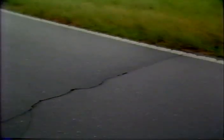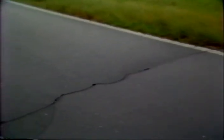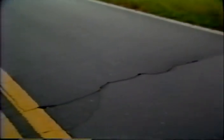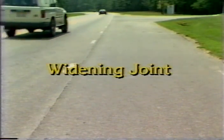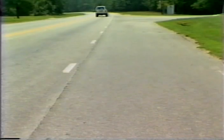Block cracks are not a load-associated pavement distress and do not represent a structural failure of the pavement. However, if these cracks are not sealed, water can freely enter the base and subgrade. This will weaken the pavement and lead to structural problems. A widening joint also needs to be sealed when open. Usually, a crack will form along the joint between the original pavement and the widening strip.